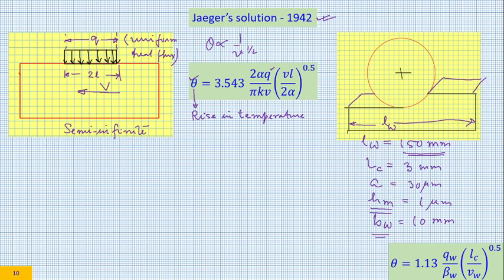What about this one, which is uniform heat flux? This we are making, I should not say mistake, but we are making a departure. What is that departure? This is the chip load, and because this is the chip load, HI is constantly increasing. As HI is increasing, FTI, that is instantaneous force coming onto a grit, that would also increase.